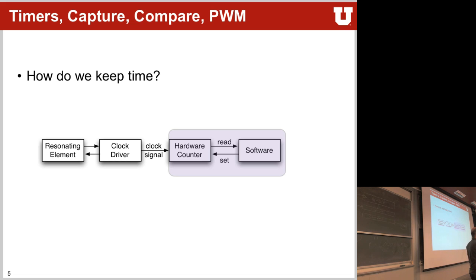So it's 2 to the 14, right? You notice this is 2 to the 15. So to get to 2 hertz, it's just 2 to the 14 counts, half of this one here. So you have 32,768 clock ticks per second, and when your counter reaches 2 to the 14, half of it, you will be at your period.